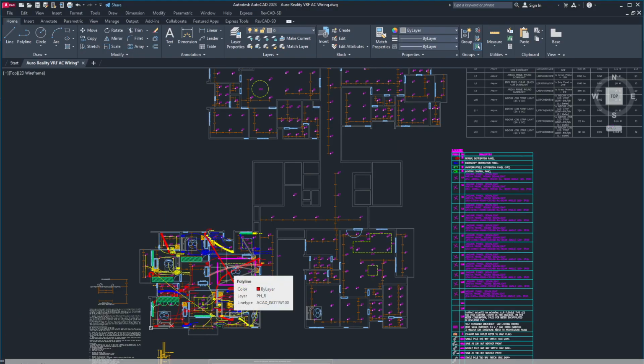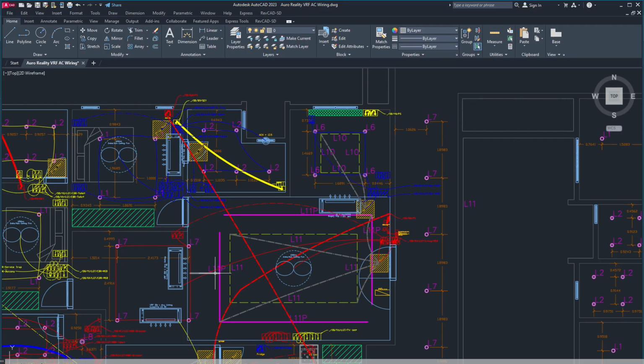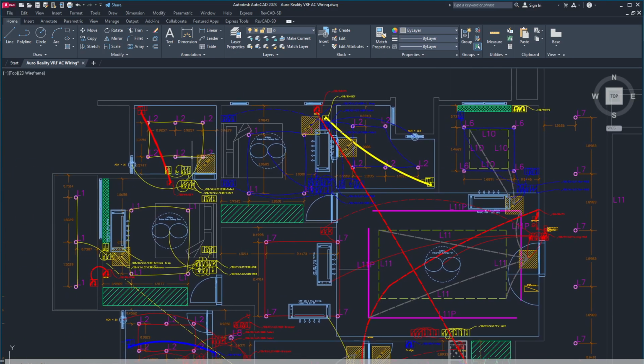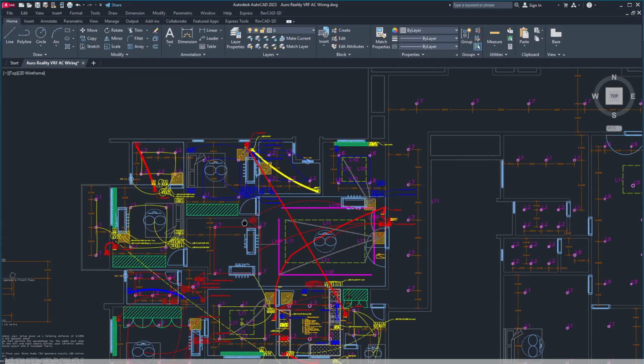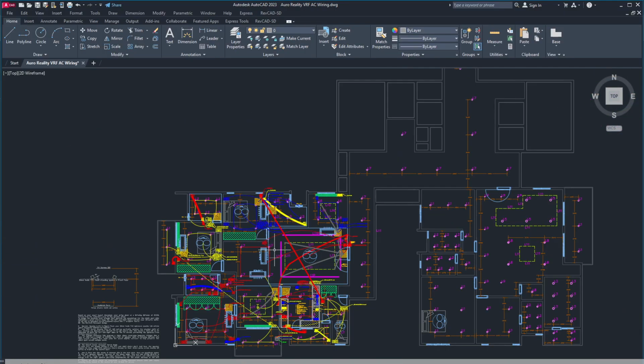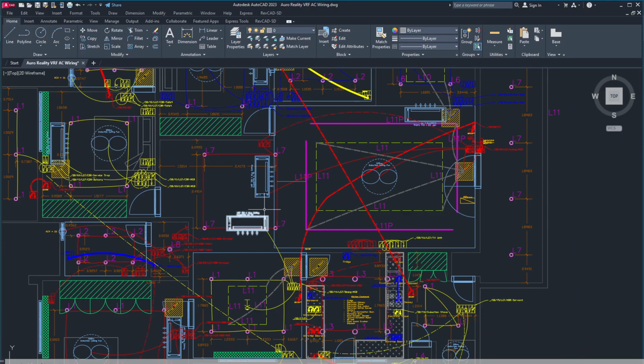If it's a double bedroom, then there will be a single phase. So for single phase, there is no phase separation and all that. So it is very less complex, so an electrician can take it up. But for 3-phase, it has to be balanced. Most importantly, if you are constructing a builder house for 3 floors or 4 floors building, and you are installing a small transformer, then it is very mandatory that you get this analysis done.